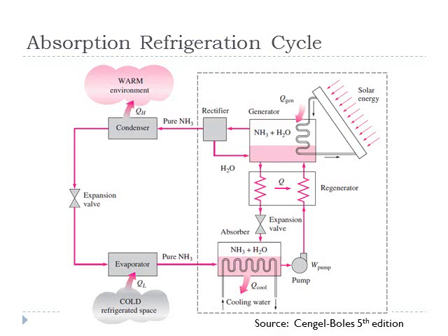Since ammonia absorption depends on the temperature of the water, we want to keep the temperature of water as low as possible, and for that reason we use a cooling water stream which is continuously cooling the absorber. Since this mixing process of ammonia and water is an exothermic reaction, there will be some heat generation, and the cooling water will take away this generated heat from the absorber.